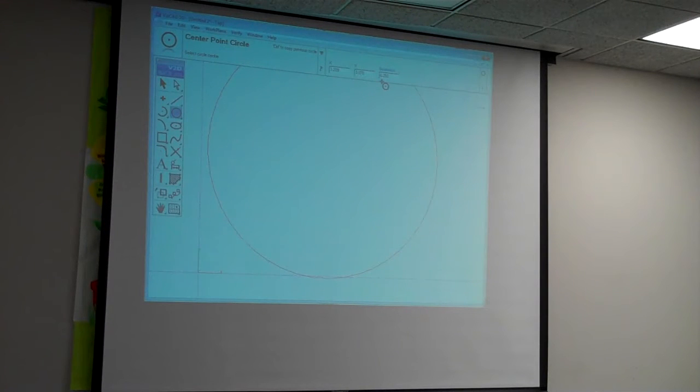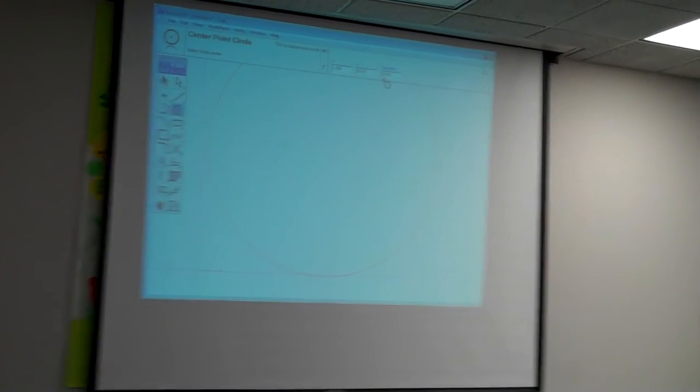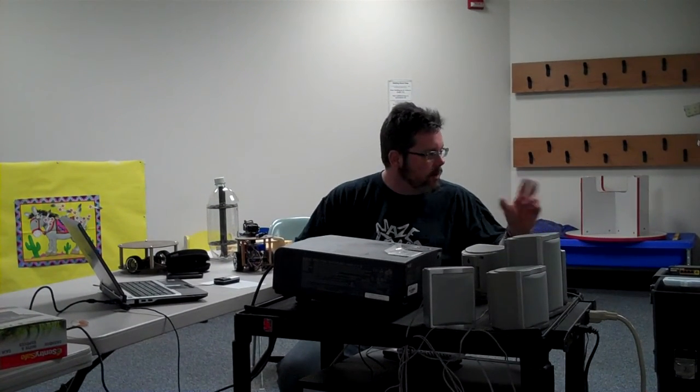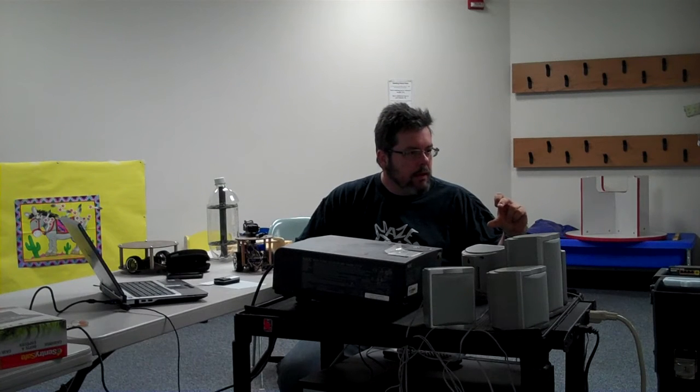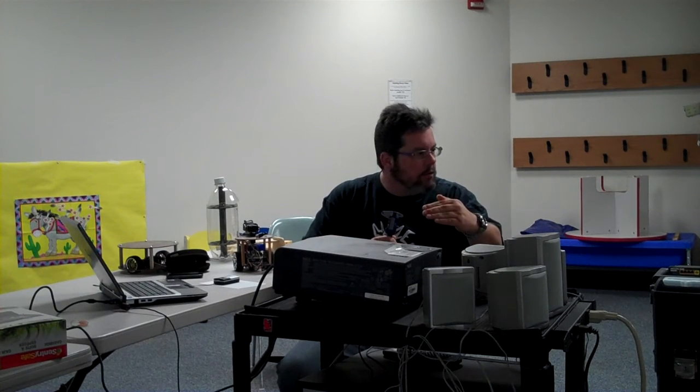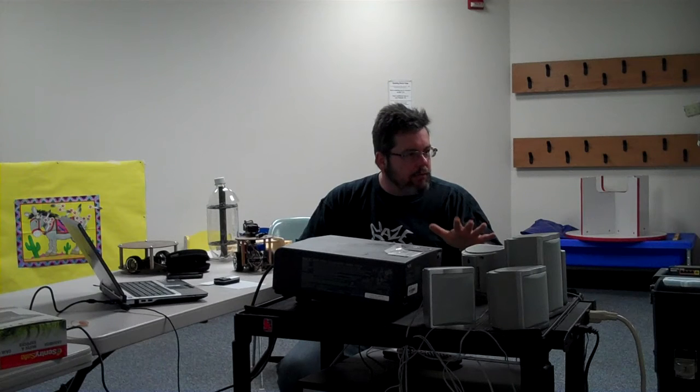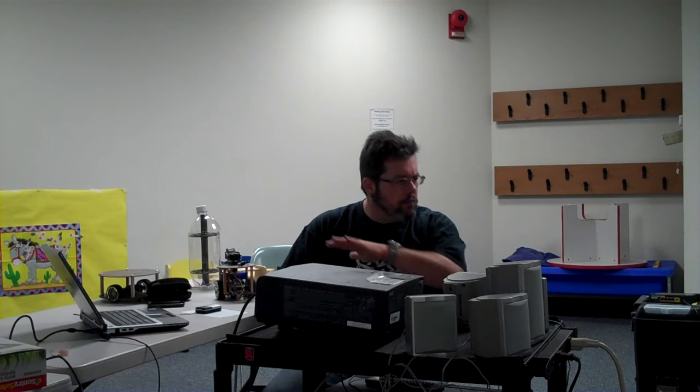Where that comes in handy is if you're measuring out a part, or somebody's already measured something out online, and you're looking at the dimensions, like it says a servo is 30 millimeters or something. Well, I can just type in 30 millimeters, and it'll convert it to inches for me. You have to decide if you're going to use millimeters or inches the whole way through your path, so to speak. You don't want to draw it up in inches and then convert it to millimeters in your CAM program and then try to cut it out with your CNC machine back in inches again. It confuses things. You want to keep everything the same.